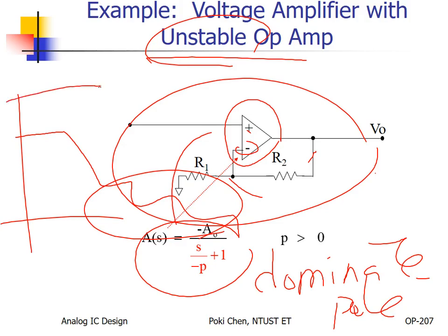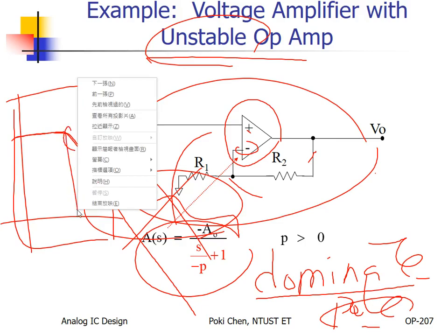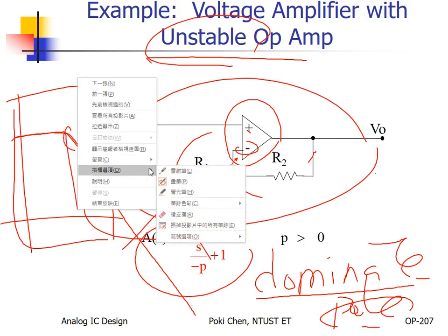If we focus on the band we are interested in, 如果我们只聚焦在我们有兴趣的那个频带, we can find it looks much similar to only one pole in the frequency response. This is the so-called dominant pole approximation. We learned already from microelectronics. So it means the circuit can be simplified with a single pole. Okay, that is the usual case.